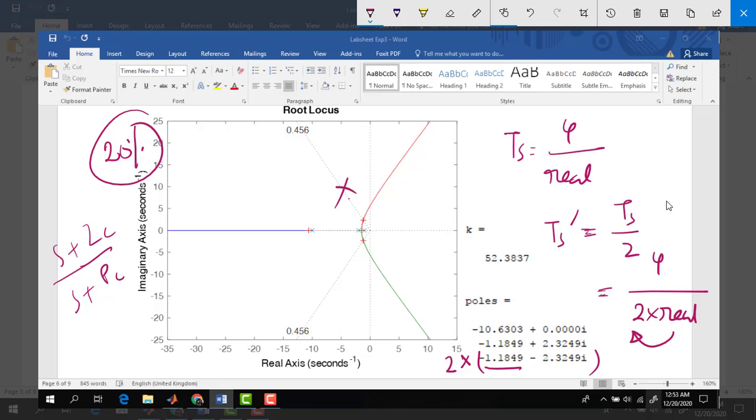Let's say we have 3 poles here, and as you can remember from the theory class, if any random point is on the root locus, then at that point the contributions from all the poles and zeros equate to an angle of -180. Let's say this is a random point on the root locus at present.